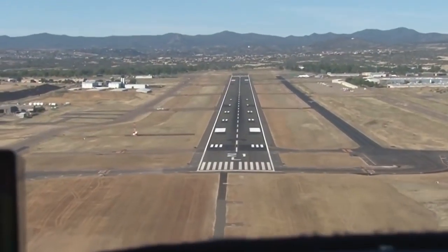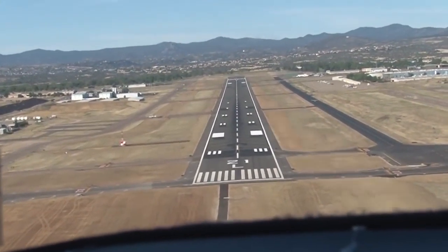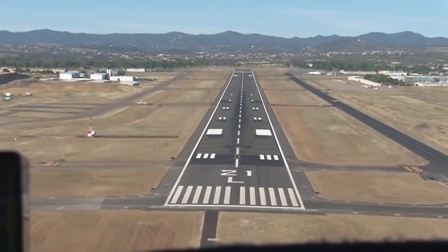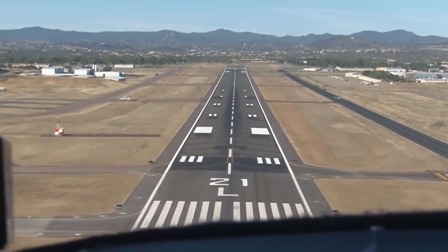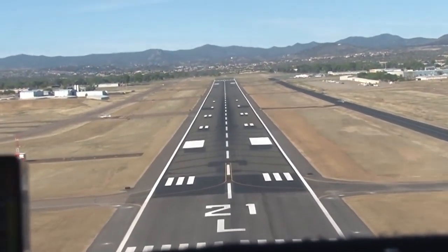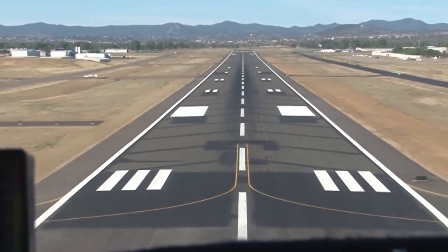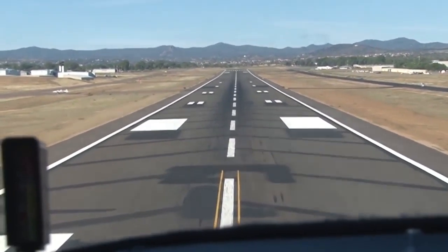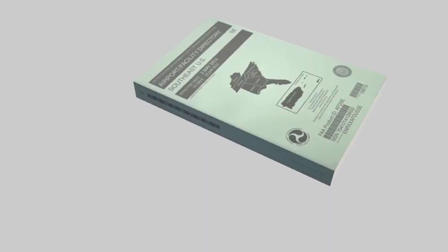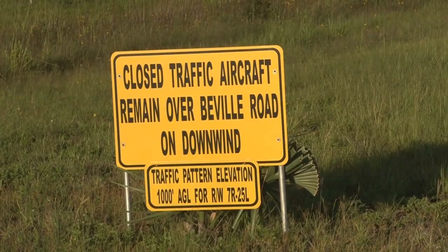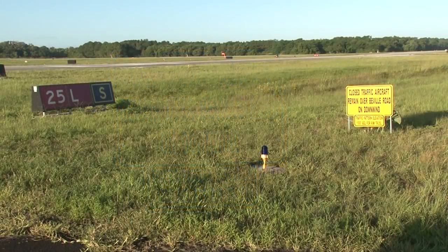As airports become encroached by homes and developments, the pilots and airport operators may have to deal with noise complaints. At some airports, the pattern procedures may be amended to minimize the overflight of the more noise-sensitive areas. Nighttime curfews or restrictions to training activities such as touch-and-go landings during certain hours may also be in effect. To find if noise abatement procedures exist in an airport, you can consult the AFD or similar publications. When noise abatement procedures exist, informational signs outlining recommended procedures are often posted near the departure ends of runways.